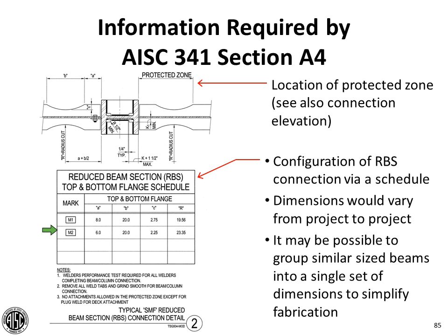By doing that, again, we can simplify the information and promote consistency rather than have things change on every single frame girder. Now, sometimes it's not as easy to make that work, and you may end up with more than just the two that are shown on here. You also, as I said, need to make sure that you still satisfy the requirements of 358 with the groupings that you use. In this case, you'll notice that the engineer has shown the A, B, and the C dimensions, and then has also shown the R dimension.